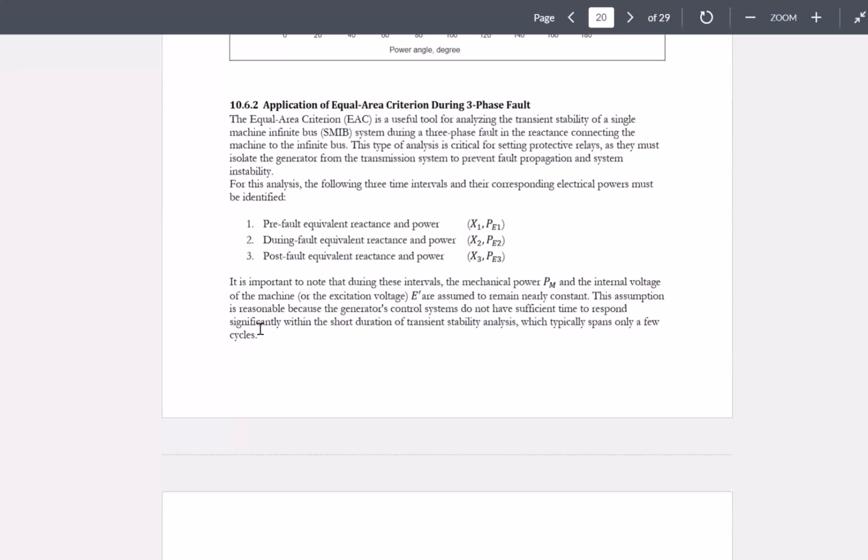Changes that happen on the electrical side are even more important. Usually you do not push power on the mechanical side that much. You cannot even do that physically because the system has inertia on the mechanical side. Even though you want to increase the mechanical power all of a sudden to a big value, because of the inertia it takes some time to get to that point. So the extra mechanical power push is not really feasible physically in real time. That PM cannot suddenly change from a small value to a very big value.